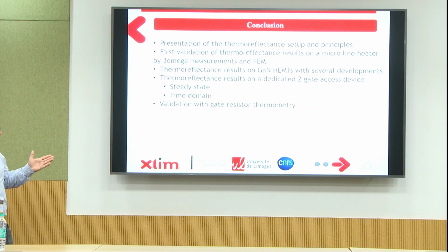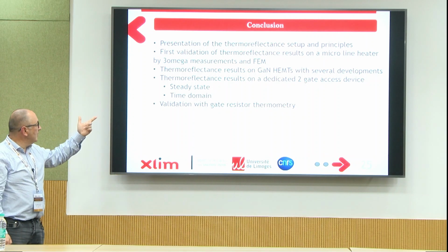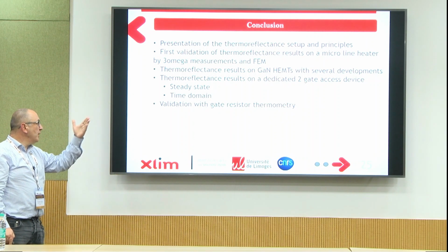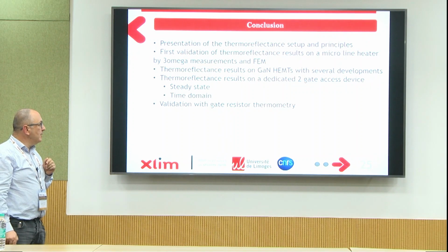So to conclude, I have presented some results concerning thermoreflectance measurement on GaN HEMT that can be performed either in steady state or in time domain. We have obtained also good results with a dedicated device with two-gate access. Future work will concern the development of thermoreflectance measurement on a device with DC bias, but also with DC plus RF power.